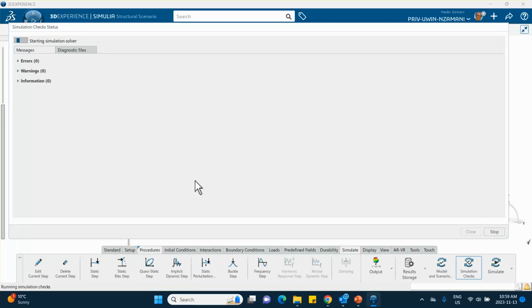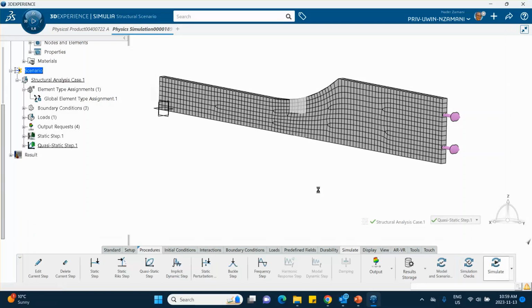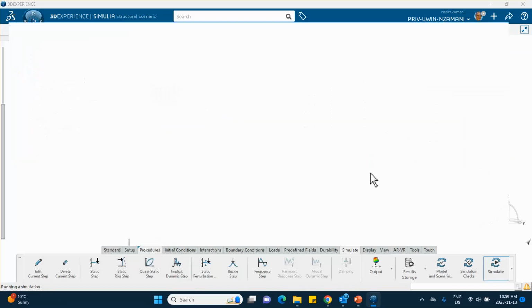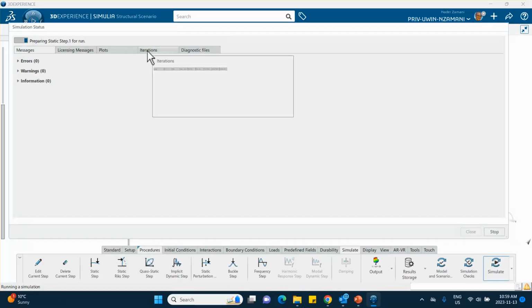And by the way, that large deformation that I activated, even if you deactivate it with nonlinear geometry, the results are not going to be much different. I didn't try it, but okay, so almost done. Good. And finally, we're going to simulate, which means actually you submit the job. And now it's going to be running. Once you say OK, and this thing pops up, it's going to be running. Click on the iteration.